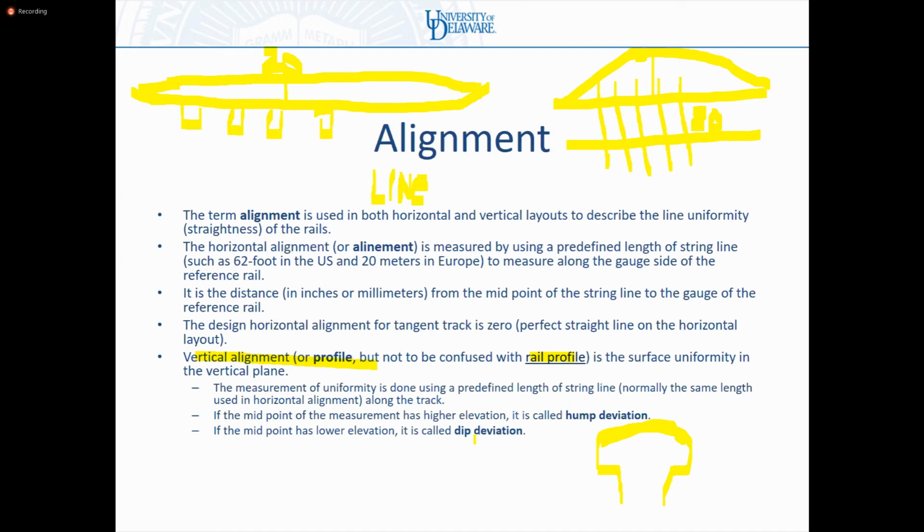I agree. But with an inertial measurement system, I'm jumping ahead of myself, but basically, you measure what's out there, right? You just get exactly a map of what's out there on the surface of the rail. But then you define it mathematically, since most standards are written in terms of chord length, even today.